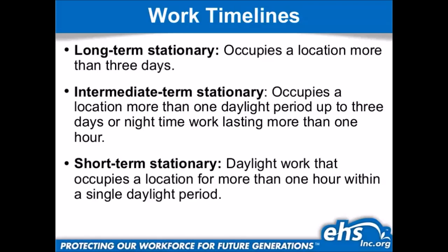Intermediate term stationary occupies a location more than 1 daylight period, up to 3 days, or nighttime work lasting more than an hour. Short-term stationary: daylight work that occupies a location for more than 1 hour within a single daylight period, so more than 1 hour up to a day.